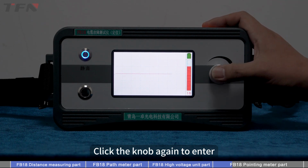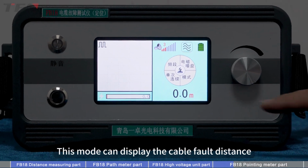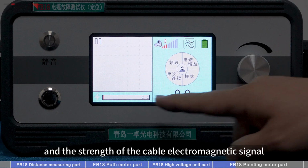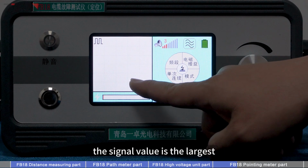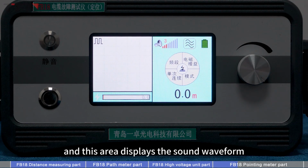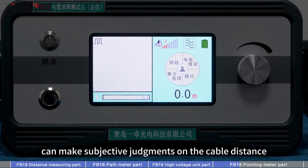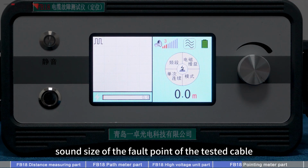Click the knob again to enter the acoustic magnetic fixed point mode. This mode can display the cable distance and the strength of the cable electromagnetic signal. When it is directly above the cable, the signal value is the largest, and this area displays the sound waveform. The sound waveform display can make subjective judgments on the cable distance and position based on the discharge sound of the fault point of the tested cable.